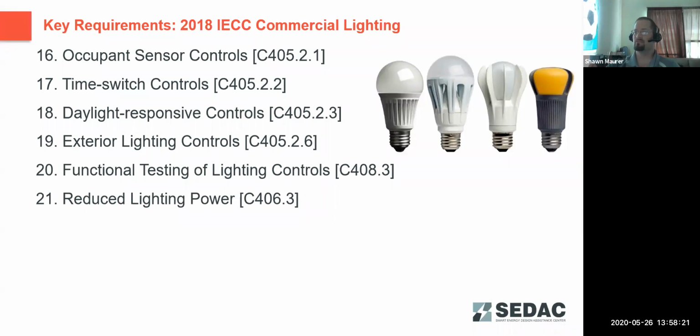Do we think recovery wheels will go away given the concerns over COVID-19? I do not think they're going to go away. There are some provisions and recommendations from the CDC and ASHRAE to, as long as it's permissible for the building system, increase outside air to try to dilute any kind of germs or microbes in the air in the building. But really, when it's very hot outside, very humid outside, you're still going to want to use those energy recovery wheels